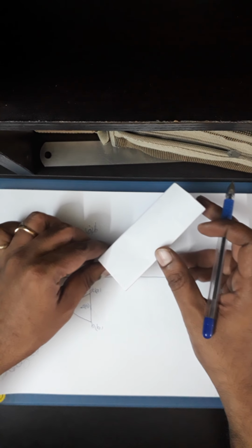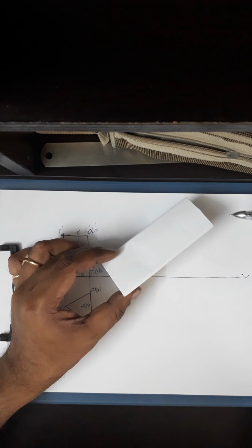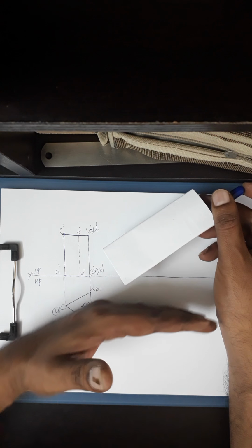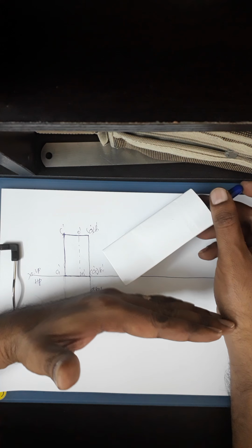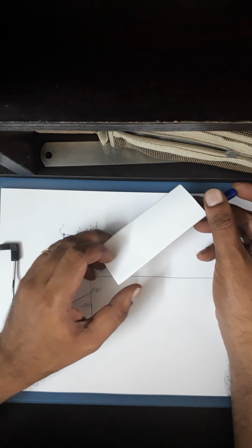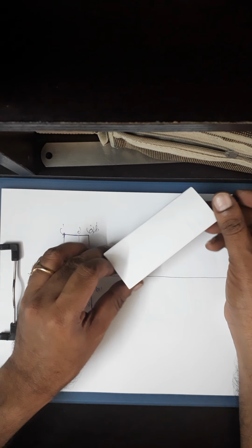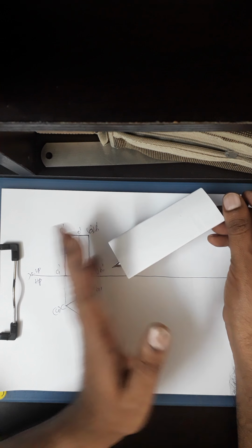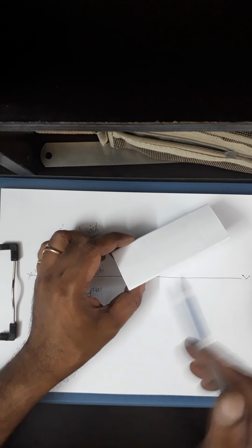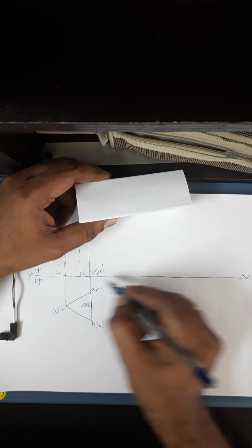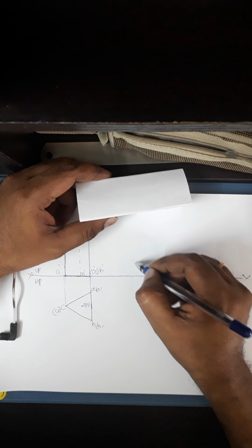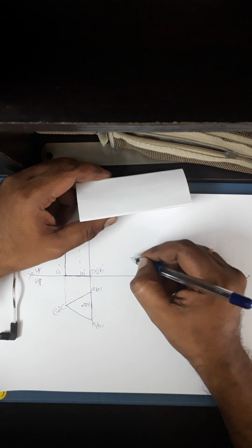So go on inclining. If the axis is inclined, this is the axis, right? So the axis is inclined at 30 degrees to HP. This is the horizontal plane when you are looking at the vertical plane. If this is the vertical plane, this is horizontal. So the axis will be inclined at 30 degrees to HP. Then automatically we'll see that the base will be inclined at 60 degrees. If the axis inclines at 30 degrees, the base will be inclined at 60 degrees because they are mutually perpendicular. I'll show you that by drawing the base. Instead of drawing the axis inclined at 30 degrees, I'll draw the base inclined at 60 degrees. Then I'll show that the axis will automatically incline at 30 degrees.